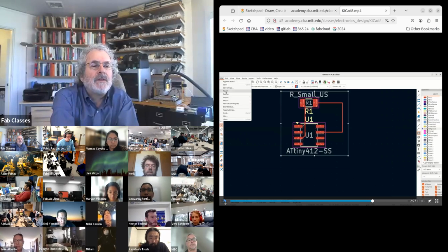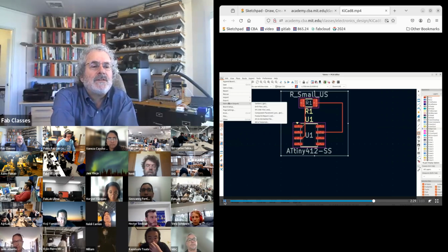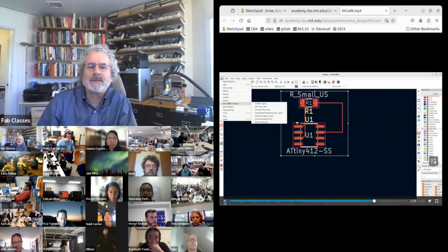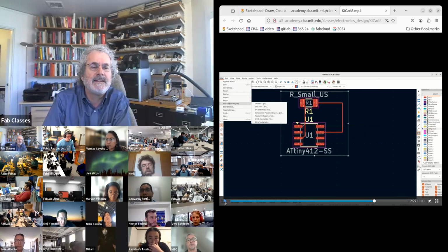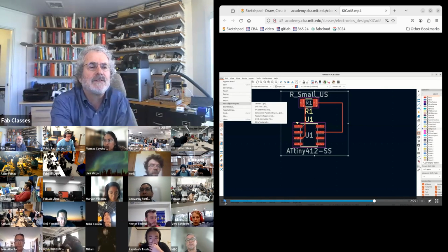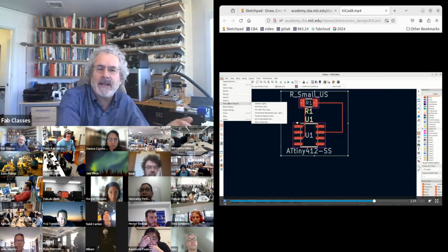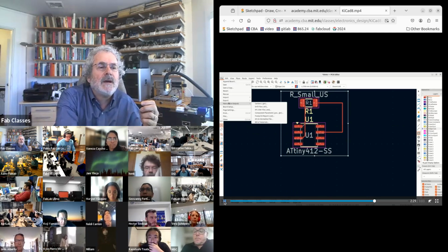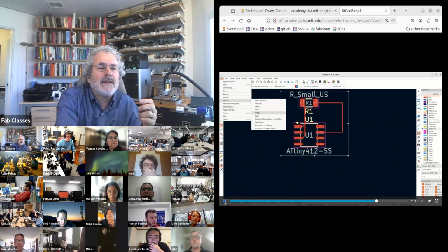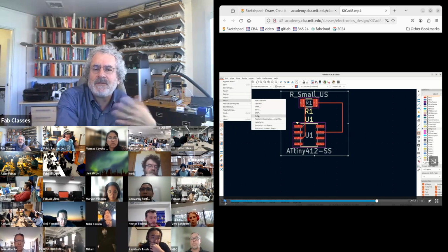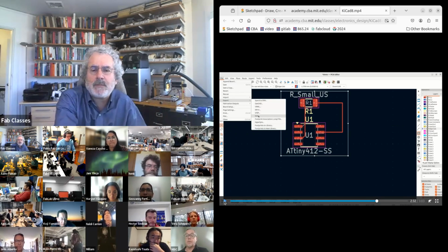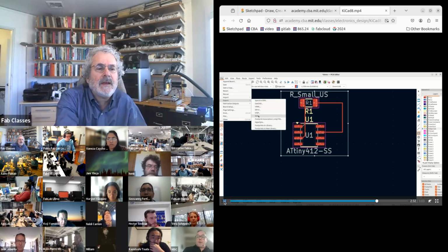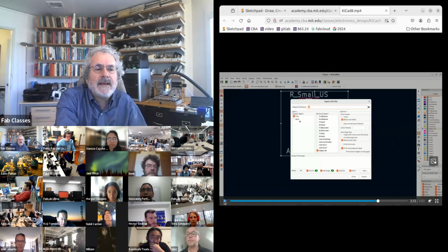Okay, now I need to make the board. So if you send it to a board house, universally they take Gerber files. And so the fabrication output lets you send out Gerber files. But in addition, you can export other formats. And for in-house prototyping, you can export SVG. So I'm going to go to the SVG export.